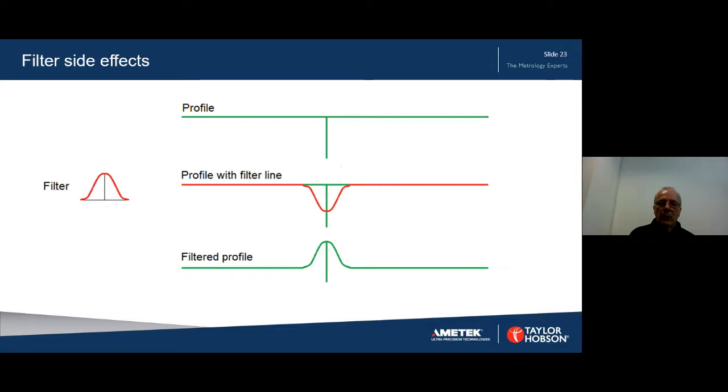When the waviness profile is subtracted from the primary profile to create the roughness profile, the area around the spike will be raised in the roughness profile. This means that the depth of the valley is now less than expected, and there is an outward going peak in the roughness profile that is not present in the primary profile and does not represent the true form of the surface.